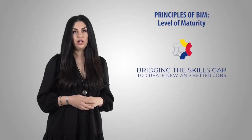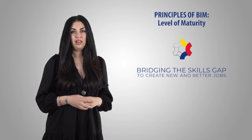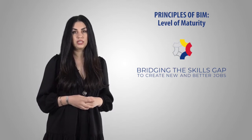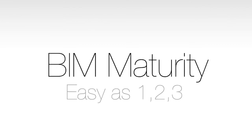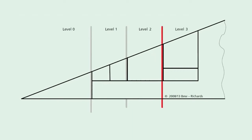You may have already heard about BIM levels of maturity, and you probably wonder what does it actually mean. The levels represent the BIM maturity regarding the ability to use and exchange information. They run from 0 to 3. Level 0 is basically the use of CAD, computer-aided design. It's mainly drawing using vector lines in 2D or 3D. Let's just face it, that is not BIM, but it's a progression from hand drawing.